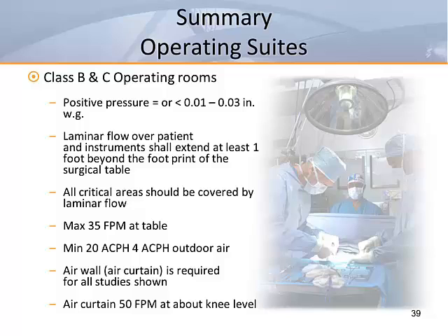Standard 170 requires a minimum of 20 air changes per hour in the operating room, of which a minimum of 4 air changes per hour must be outdoor air. While not required by Standard 170, we recommend including an air curtain in the design where critical surgeries are performed.